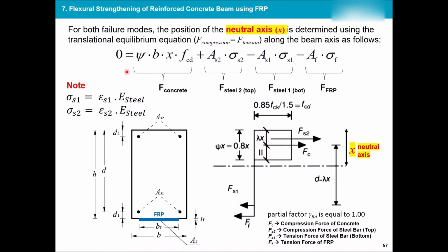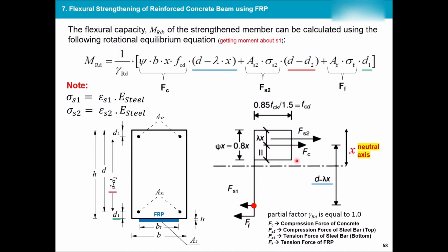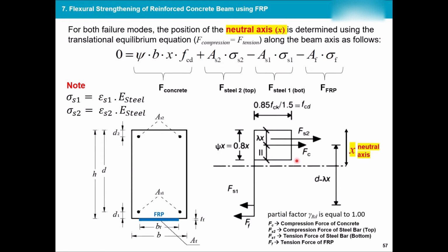The only formula which is a little bit complex over here is concrete, which relates back to the studies that you have already done on how to analyze a section. But there is an easier way as well. Now, looking at these forces, they all have a distance to a point. Don't you remember, moment was force times distance? Moment was force times perpendicular distance.